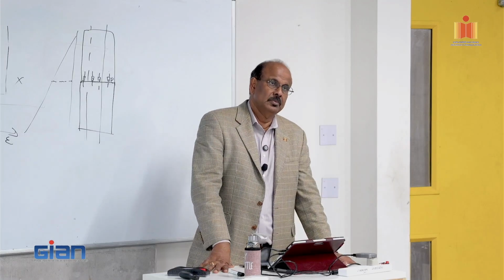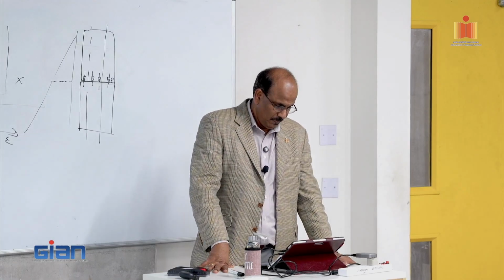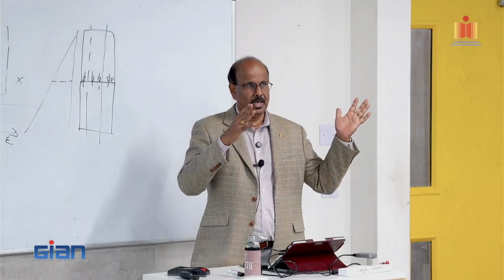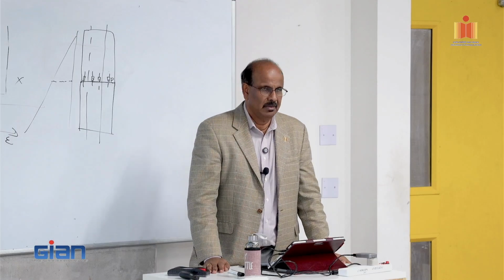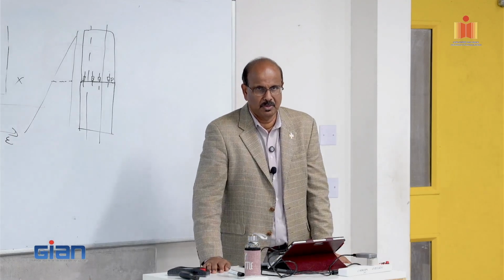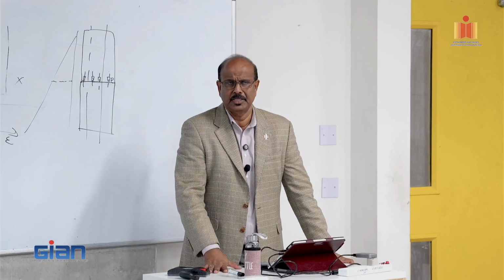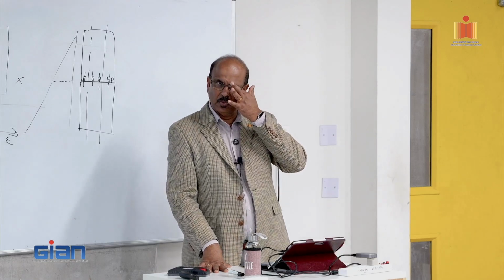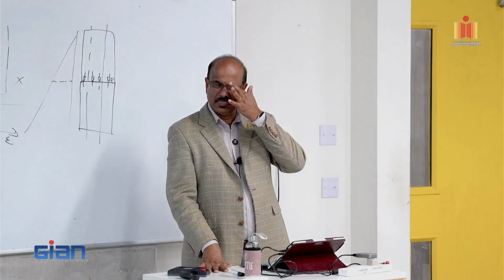Typically, the self-centering nature, so when it goes back and forth after the earthquake, they come back to their original position. That's a huge benefit of the system compared to cast in place. The elastic force in the pre-stressing system basically brings the structure back.